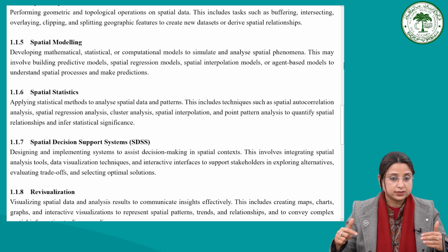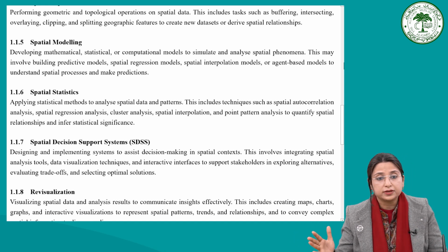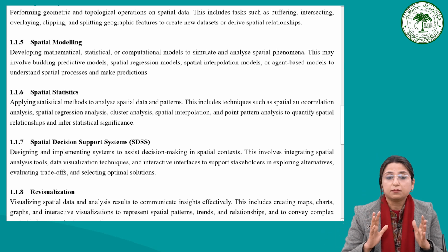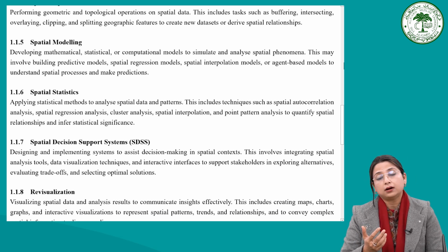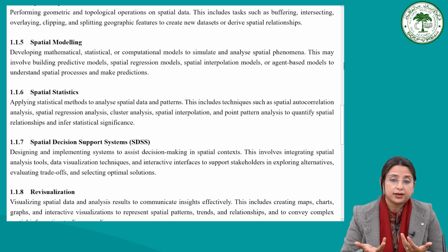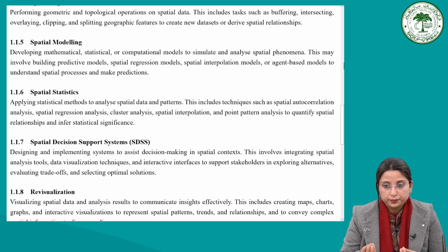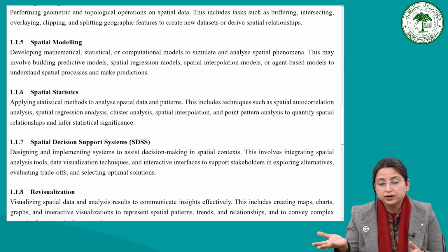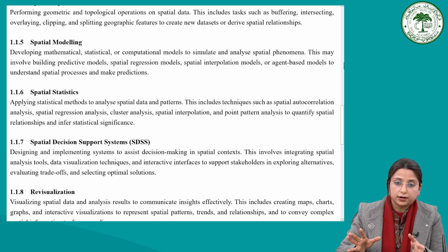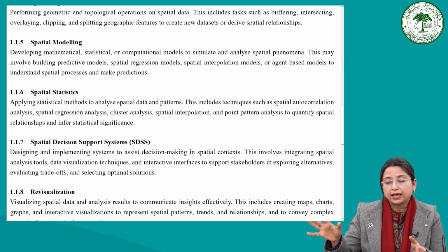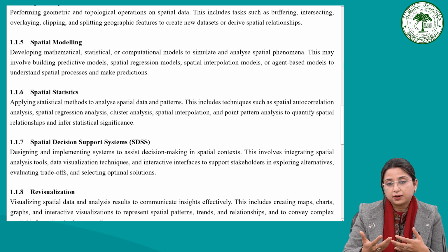Spatial modeling deals with the spatial unit. Certain models are to be used, and these spatial models may be mathematical, statistical, or computational models that can be used to simulate and even analyze spatial phenomena. For example, to simulate the future land use land cover, we can use a model like the Markov model to simulate the future land use land cover map. So by applying that model, we can predict the future land use land cover.